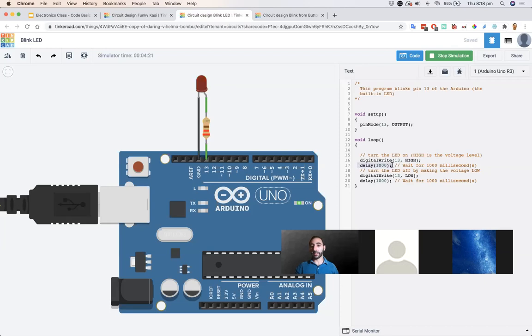The next one is a delay. So the function delay just says, go into this and wait until a certain amount of time has elapsed. So the input to this function, inside the parentheses, the brackets, is 1,000. The thing about writing in Arduino is the default in here is milliseconds. So there's 1,000 milliseconds to a second. So you can see that by milli. So if we put 1,000 in there, it's going to be 1 second. So it's turned it high, and then we've waited 1 second.